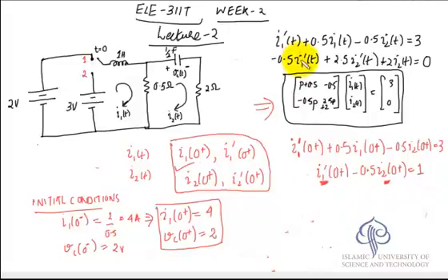Now let us see the second equation. Since we know the capacitor voltage at 0+, let us use this information to simplify the whole thing. We can combine the two differential equations by writing the mesh equation for the bigger mesh outside, and this would help us in solving the problem slightly more easily. So let us write down the mesh equation for the outside mesh at 0+. That is basically combining the two equations together and then putting t = 0+.